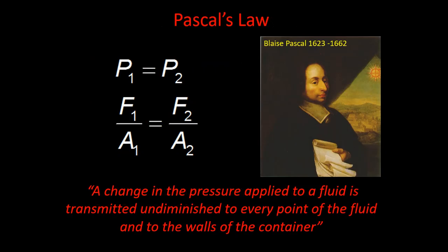And looking at Pascal's law, here's a picture of Pascal himself with a very ornate sun in the sky behind him. Pascal's law can be expressed in the sense of the straw we were just looking at, in equalizations of pressure. So here, P1 is equal to P2, and that gives us, substituting for pressure, F1 over A1 is F2 over A2. And Pascal's law in words makes this statement. A change in the pressure applied to a fluid is transmitted undiminished through every point of the fluid and to the walls of the container.